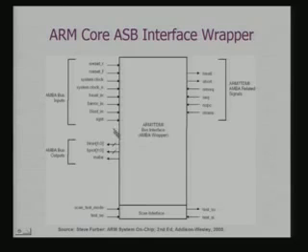Also the size information, which we provide in the AHB bus, would be obtained from the outputs provided by the ARM chip. So this is basically an interface unit. With the CPU core, typically you design an interface unit to provide it with the ability to communicate on the AMBA bus.